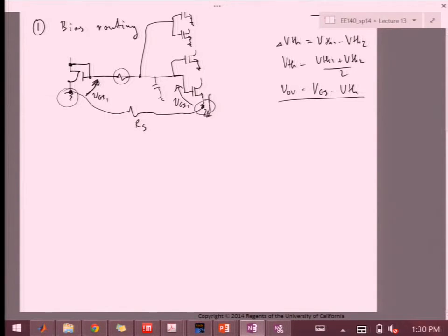Okay? So if that happens, what does this circuit remind you of? I have a diode connection here, and then where I'm mirroring, I have a resistor in the source. Yeah, the one we just analyzed, the Widlar source, or the Widlar current mirror.